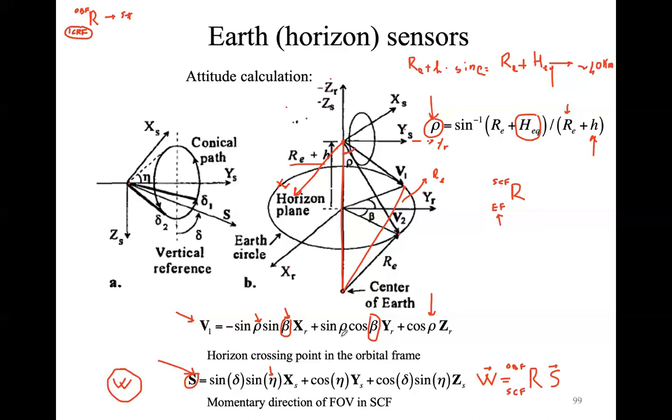The problem you have is that when you deal with equations that give you the position, the center of the reference frame is important. Here we are dealing with orientation. So that's the reason why, when you see this formulation, you always have to think that all the reference frames are centered at the same point.